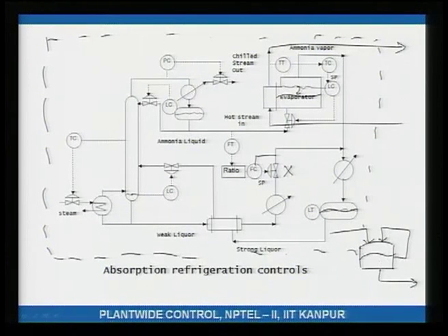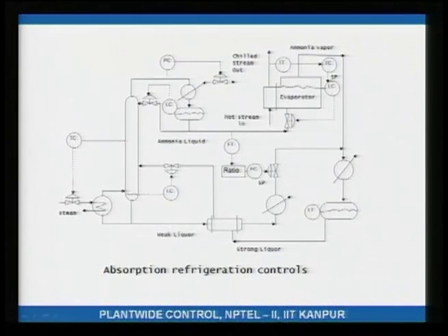Now, I can set this circulation rate at whatever I like. It's like having a tank, like I've drawn here. You have some amount of material there, water and ammonia. You can recirculate it at whatever rate you want. You don't need to control the level, right? Therefore, there is no level controller here. That's why we have this.